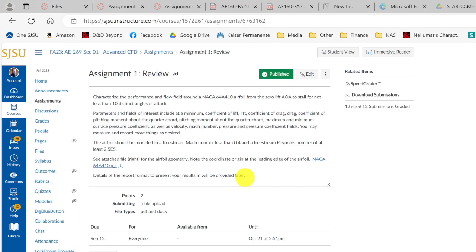And also, it's very different from what other people got. Okay. Most people at similar angles of attack, if they experienced a stall, it was a very gradual stall. It wasn't all at once. And this almost ultimately traces back to the mesh, or to the prism layer specifically. Okay. Now, admittedly, you've also got really weird, sharp discontinuities.